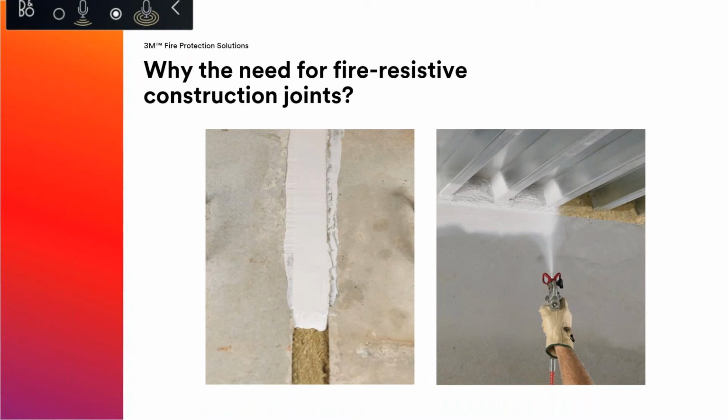However, there's an inappropriate fire stop solution at the top of the wall, or maybe no solution at the top of the wall. So essentially, even though we spent the time and the money and the effort to fire stop the through penetrations, we still have a major gap at the top of the wall for smoke and flame. So all the rated joints on the project need to be fire stopped as well.